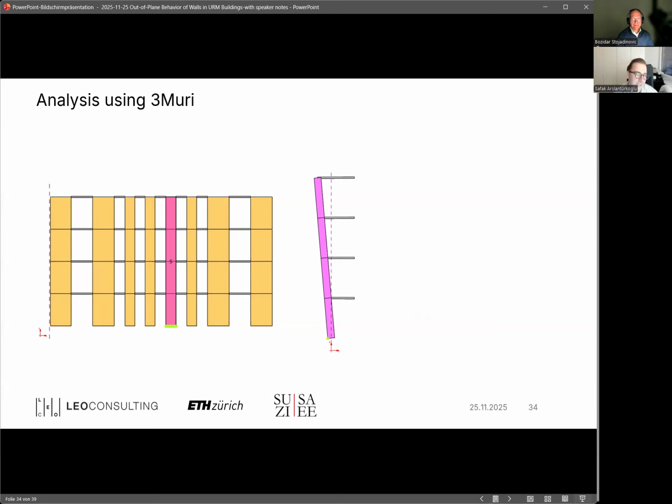And there is actually an infinite number of possible mechanisms, so it is also a bit based on experience to expect. Maybe here I expect a corner failure, or here maybe a rooftop, or in the attic because of, as you said, low axial loads. So there's some automation, but the definition of mechanisms has to be done by the user. Yeah, that is the challenge. I agree. And for some of the younger and more computer proficient attendees, that's an opportunity to perhaps develop something that could be useful for a lot of people doing this in practice.